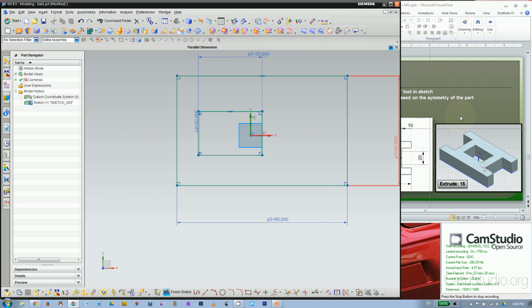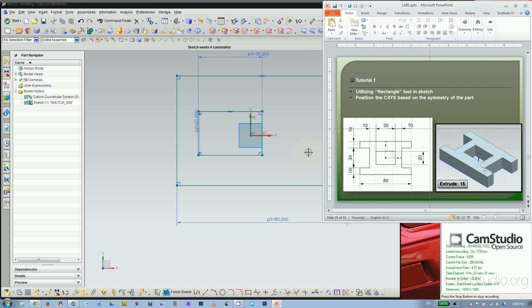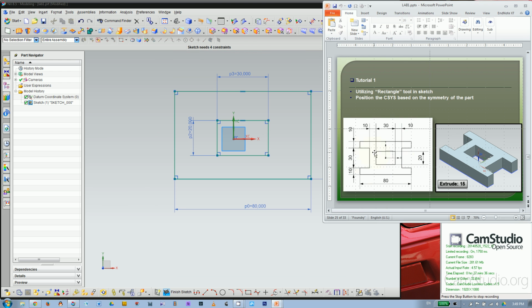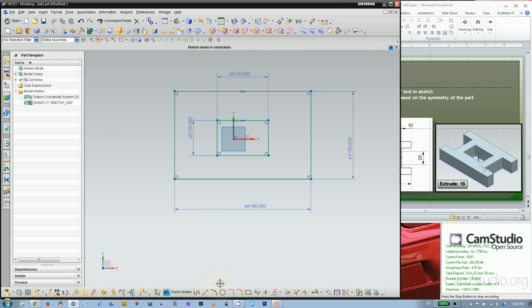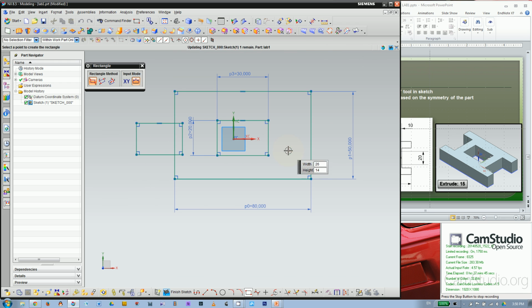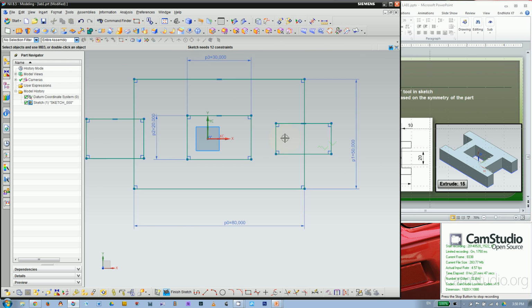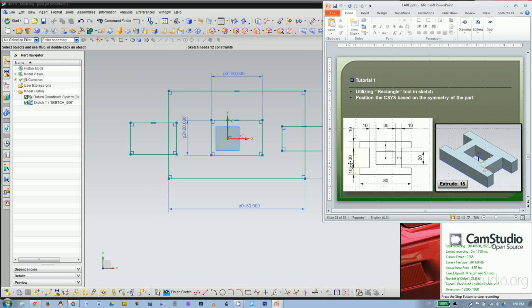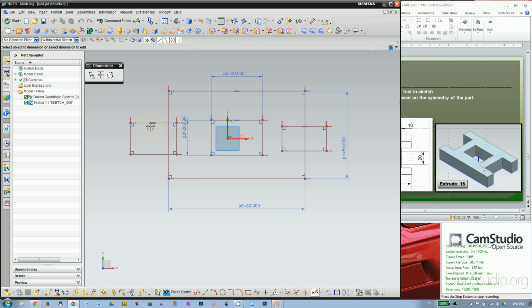All right, now we have the big rectangle and the small rectangle. We're going to create those two cutouts. So that's again two rectangles. I'm going to drop them at random distance, random dimension. Then you can look at the size. It's 30 on height, and the width doesn't matter because you're going to cut them off. So as long as it's 30, that'll be fine. Okay, 30.